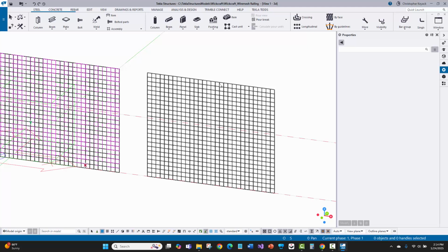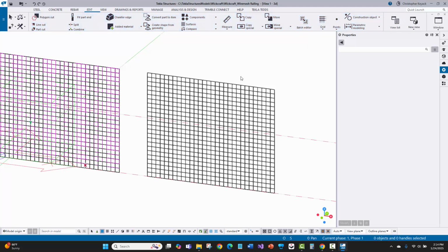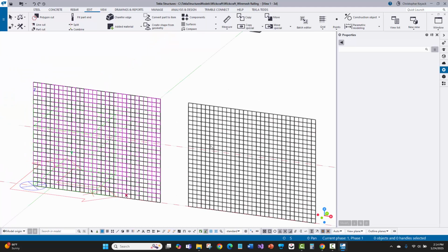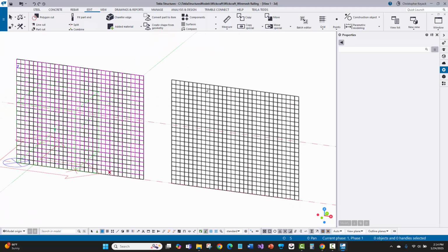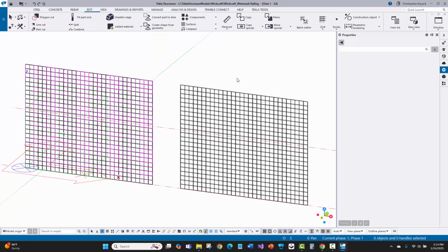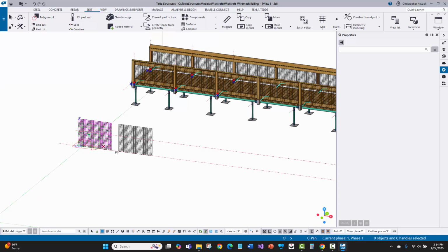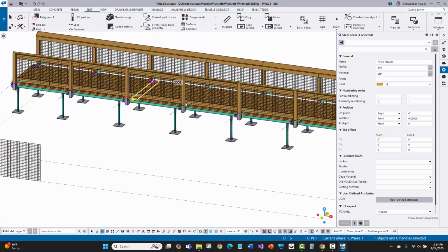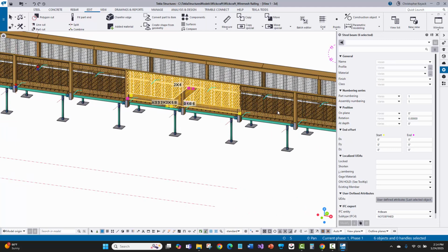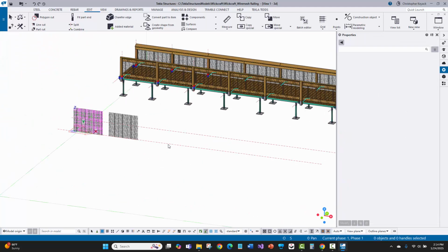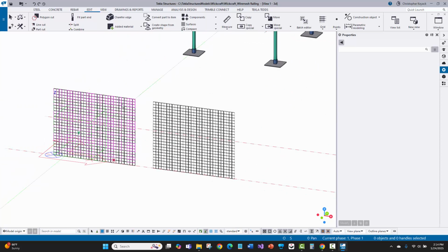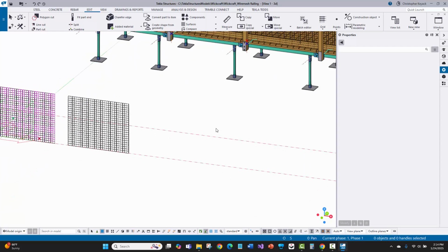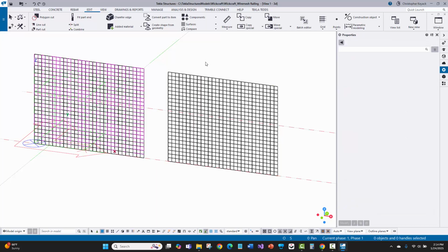You can actually cut these. So you can use all of the polygon cuts and do copes and cut this down or cut skews in these if you want to. So the item route is really great if you're going to cut special shapes from a starting point of wire mesh or perforated metal or grating and things like that. And it is lighter weight, but I didn't quite go this route for this customer because they actually wanted just one large piece across here. Now, in this case here, you'll see that I actually just made copies, so I could have gone the item route, or I did it another way where I made a custom component and an API plugin that dynamically arrays the number of bars and the part adds, so that way it can be stretched and adjusted on the fly. But I just wanted you to see that the item route is another good way to go as well.